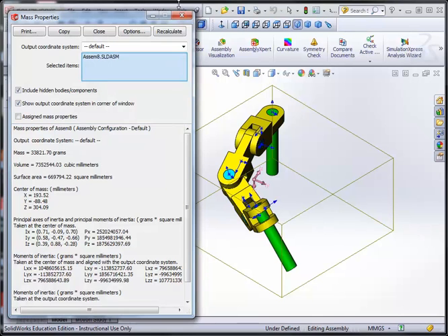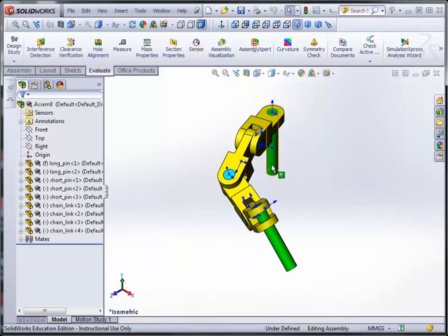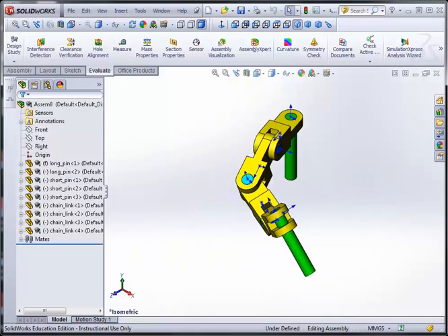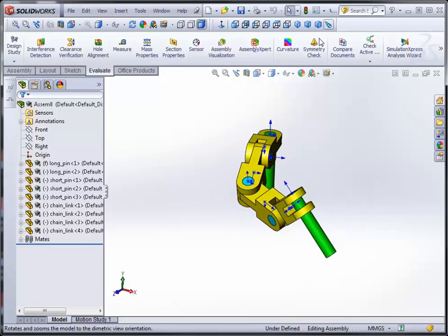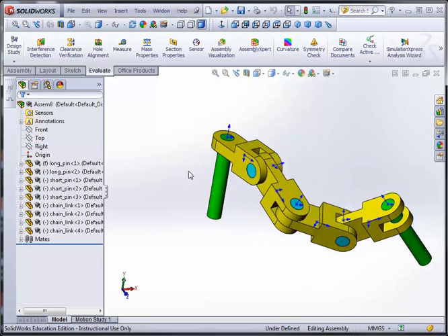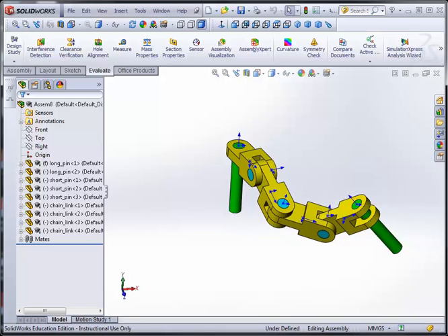So when you're creating advanced assemblies, make sure you do not rotate your assembly because it could alter your center of mass. Make sure your view is correct. The first part that you made is mated correctly with the origin, your main assembly's origin. And also keep tallying A, B, C, and whatever values you're supposed to use.